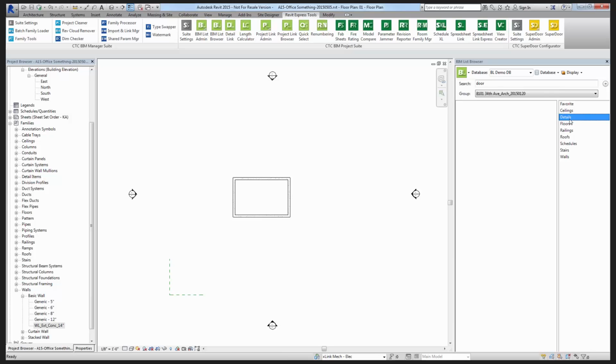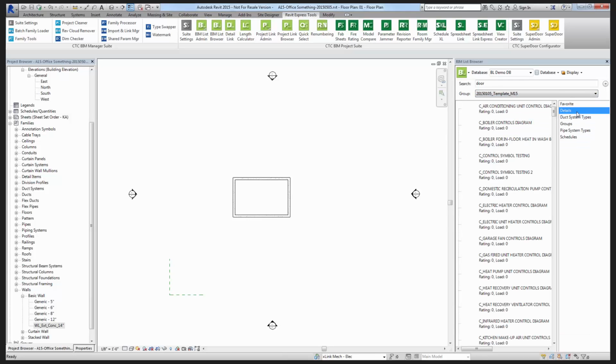And again, you can also do details. I don't have any details in that particular container file, but if I was to go to one of my other container files, let's see if I have any details inside of there. Yeah, I've got a couple of details here from my mechanical file. They're just two-dimensional drafting views is what they are. But I can take these two-dimensional drafting views, and based on the name, I could drag and drop this across from this other project into my active project, and have a drafting view that actually gets defined. So I can start bringing into my file from this other detail outside library content that I need as an end user. Easy to find. Again, I can search at the top up here for something specific.